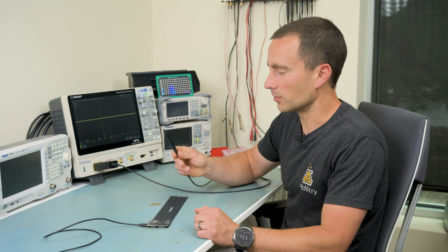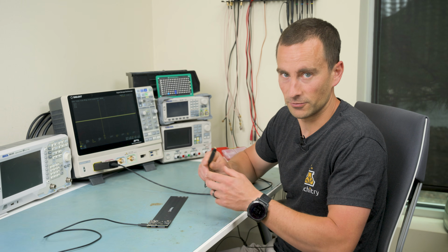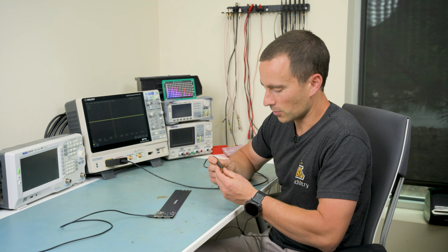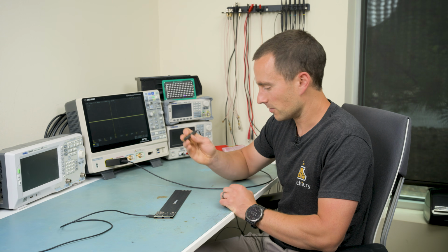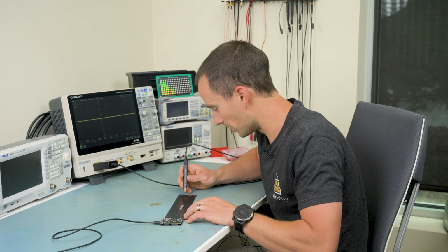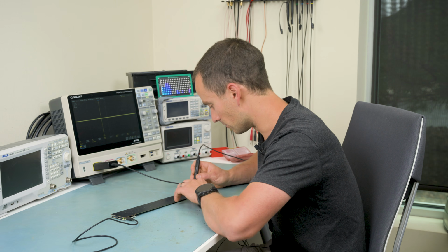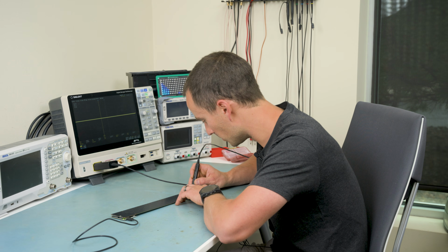Here I have an Alchitry AU set up to send 10 nanosecond pulses through the 5 differential pairs using LVDS. For this demo, I've switched out the probe to this differential probe as we're looking at differential signals. This is just like a regular probe, but it takes the difference of the 2 signals instead of referencing one to ground. And I can start by probing our reference, which is the really long trace with no mismatches.